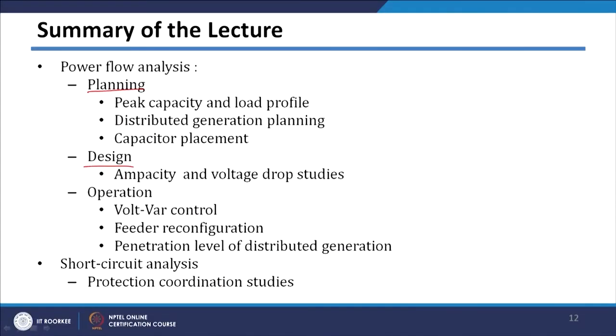So, in summary of this lecture, we have seen various applications of power flow studies. These applications include planning, design and operation. In planning, we have taken 3 cases: one is peak capacity and load profile planning, second is distributed generation planning, and third is capacitor planning. In the design stage, we have taken one case study where ampacity and voltage drop studies can be done.